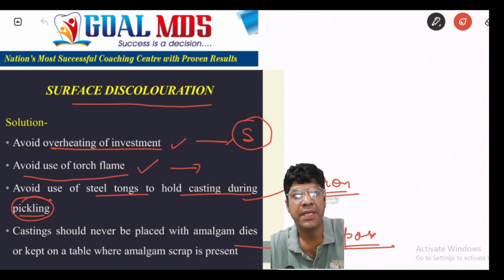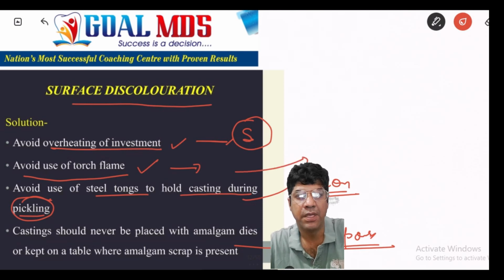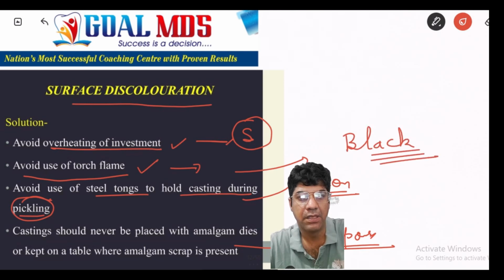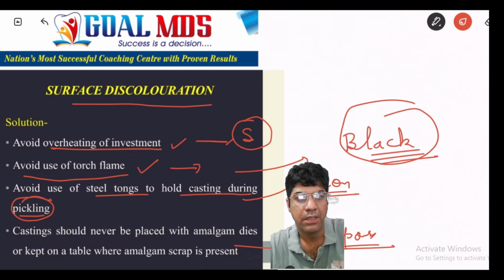Ensure complete elimination of the wax pattern during the mold heating, as incomplete removal can lead to carbonized wax on the casting, which can cause black casting. This residue can be removed by heating over the flame. The type of flame used in the casting procedure matters.